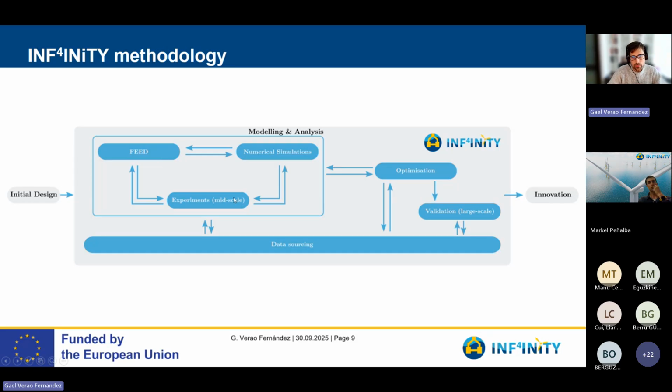So we are at the moment doing hydrodynamic analysis of the existing floater design and the existing mooring configuration. And specifically, we need to look at the operational loads to assess the fatigue. And also we need to look at the DLC standards, because we are also looking for a standardization or certification of the turbine that we are designing.